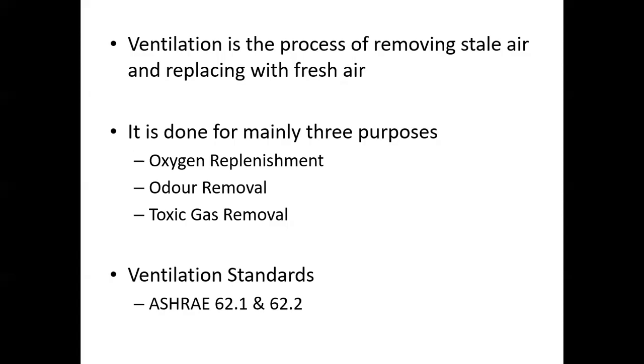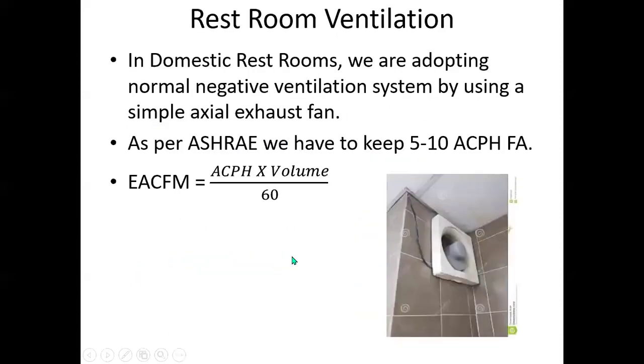Here, let's start with the negative ventilation itself with restroom ventilation. So in here also, you need to consider two different aspects: domestic restrooms and commercial restrooms. So what is the difference between domestic restrooms and commercial restrooms? It's the occupancy and the frequency of usage of those restrooms itself.